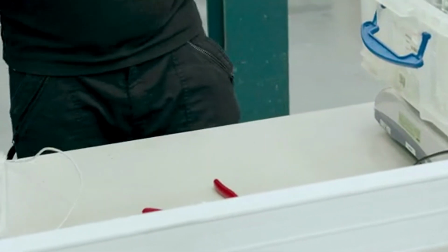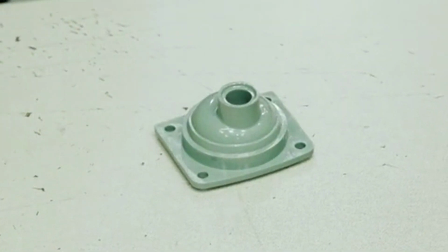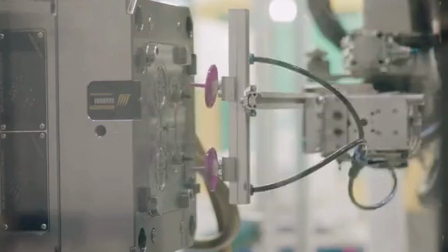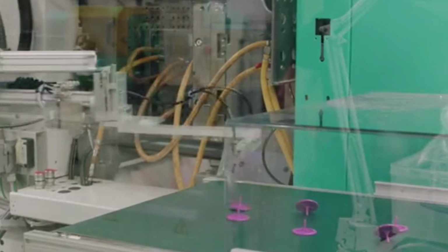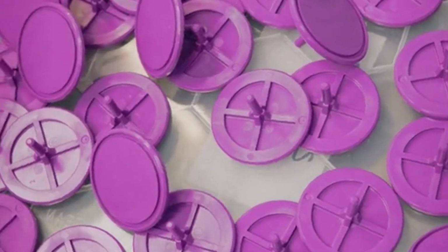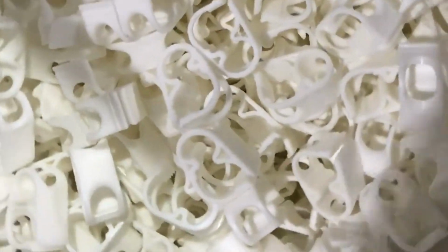For example, for a mold cavity that withstands high pressure, it is necessary to calculate its stress and deformation through mechanical formulas according to the injection pressure of the plastic material used, generally between 50 to 150 megapascals, and the size of the cavity. If the calculation results do not meet the strength requirements, the mold structure needs to be optimized, such as increasing the wall thickness or adding ribs.